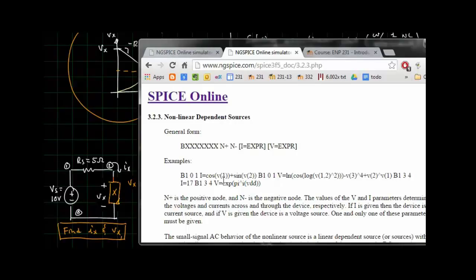One caveat: if you are using LTSpice and you can use the B source, be aware that when you want to specify something to a power, you can't use the little caret symbol, because they use that for the exclusive OR operation, since it's also a mixed-mode digital simulator.